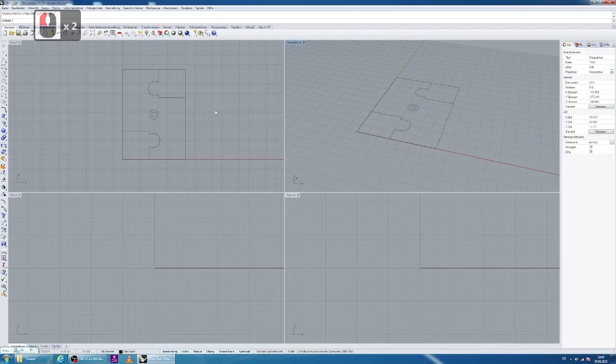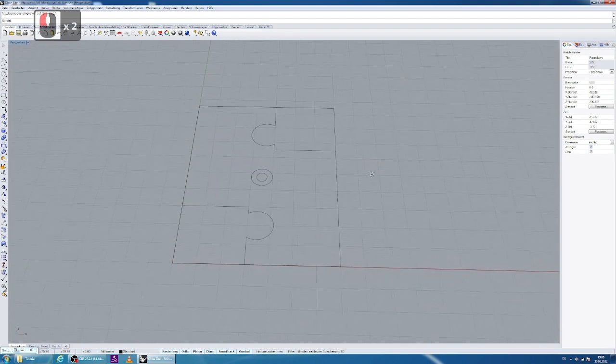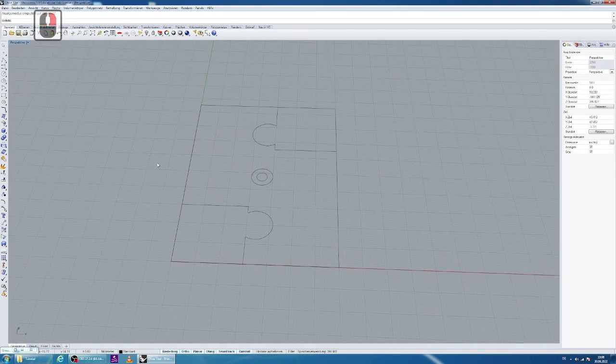Now we'll take a look at setting up the construction space for the 3D calculations. Rather than a flat curve, we need a three-dimensional volume for our construction space, inside of which the structure will now be generated. For my hook, I'm going to extrude the 2D sketch I drew earlier in order to turn it into a volume.